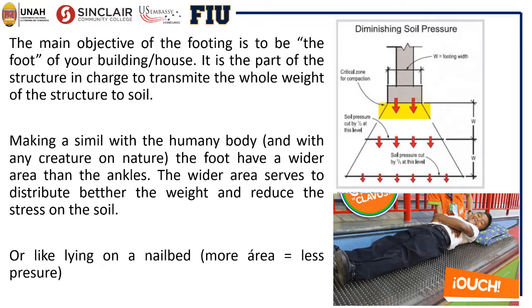Well, the main objective of the footing is to be the foot of your building or your house, and it is the part of the structure in charge of transmitting the whole weight of the structure to the soil. Making a comparison between a structure and a human body, the foundation system is like the foot, and as you can see, the area of the foot is greater than the ankle. So the greater the area, the lower the pressure on the soil.